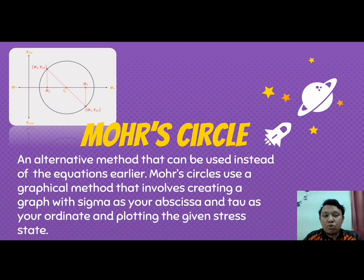I would like to briefly explain Mohr circle and its relationship with the transformation of stress. Mohr circle is an alternative method that can be used instead of the equation earlier. Mohr circle uses a graphical method, a circle, that involves creating a graph with sigma as your abscissa and tau as your ordinate and plotting the given stress state.